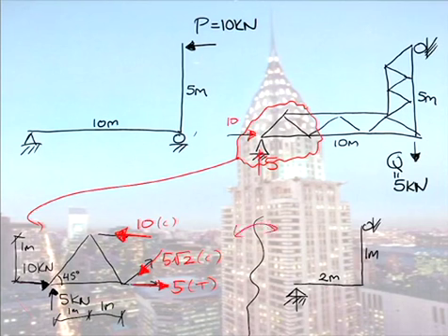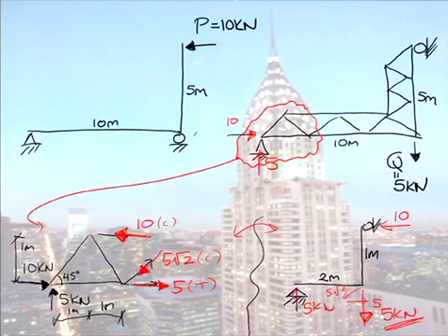Okay, if I turn this support, I'll keep this support as a pin. This 10 kilonewton, well, that now becomes my roller. These 2 other forces here, well, if I apply a force down to the left and a force to the right, that one's 5 and that one is 5 root 2. What do I have? Well, I have a resultant force down here of 5 kilonewtons. And as 5 kilonewtons is your loading, lo and behold, you get a reaction here of 10, a force up here of 5, and a reaction to the left of 10.